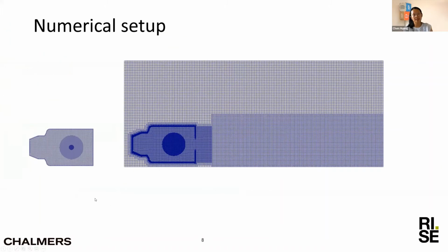What I did is that I created the first mesh by taking the CAD geometry, making it using this free CAD program, making an STL file and importing it into OpenFOAM, and making the mesh using snappyHexMesh with a finer mesh in the middle to resolve the ignition and initial flame propagation process.